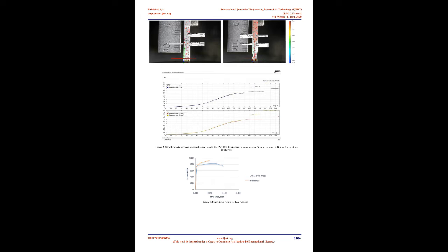Table 2, Test Specimen Geometry Description. Sample ID, gauge width in mm, gauge thickness in mm, cross-section area in mm squared. 3SN01: 2.14, 3.23, 6.85. 3WEZ01: 2.14, 3.03, 6.48. 3GW01: 2.13, 3.23, 6.88. The size of the existing miniature tensile test specimens is given in Table 2 below. For the calculation of the engineering stress-strain curve, we take the value of cross-section area given in the same table.